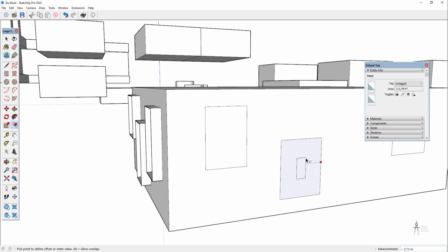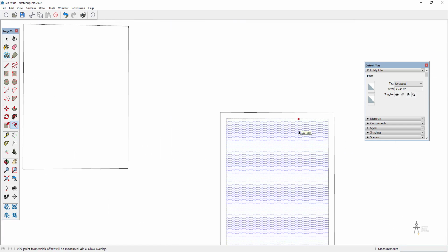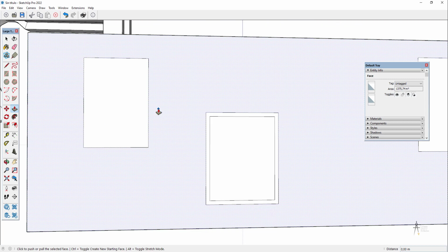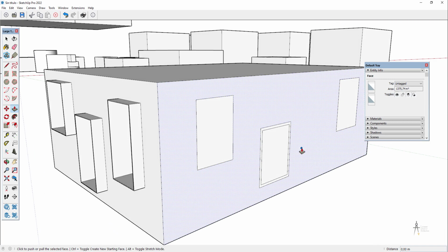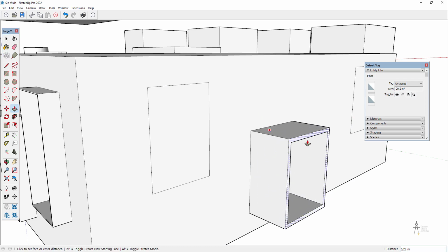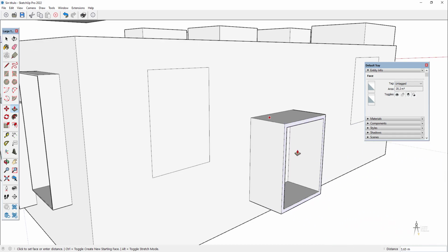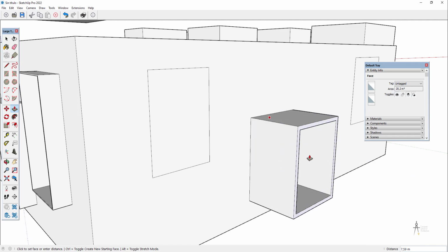Another way of going through this process would be clicking on the first window, deciding my offset, let's imagine 0.5, enter, and then doing my extrusion, select the face, push. This is basically the same but in a different order. How much?